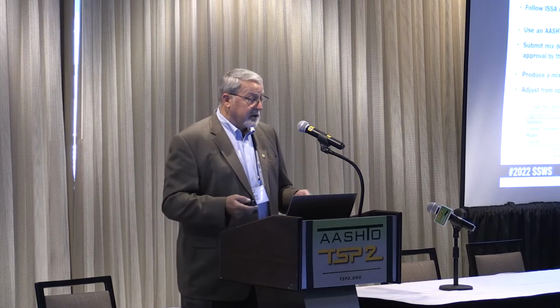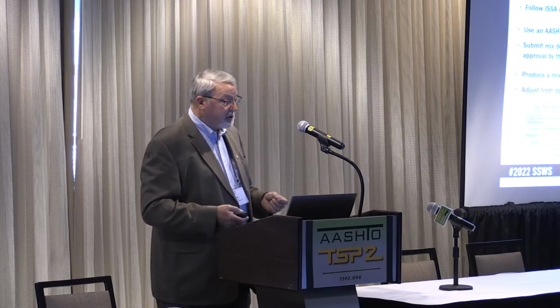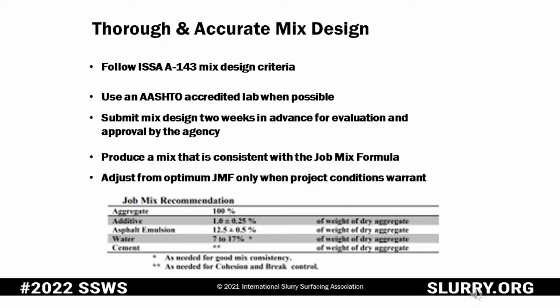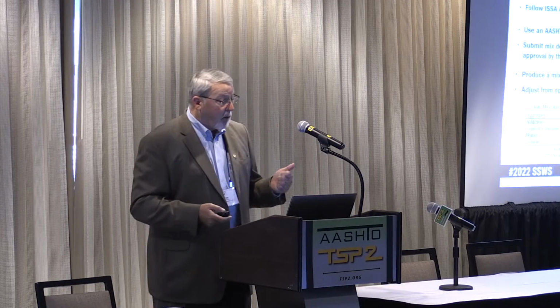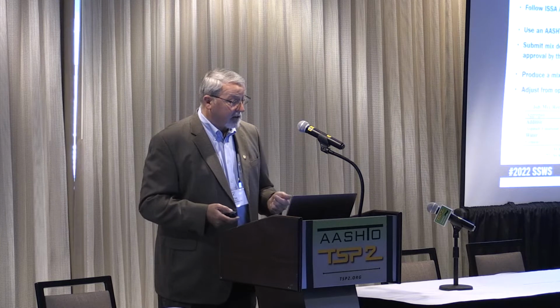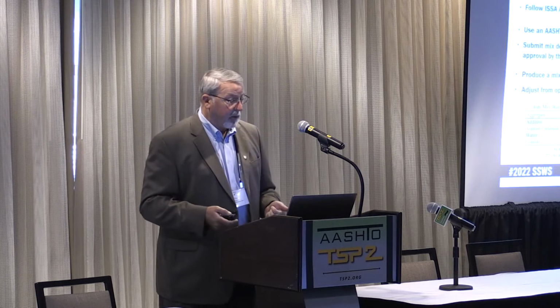You want to make sure that the contractor submits that mix design at least 2 weeks in advance for evaluation and approval by the agency that's going to be performing the oversight on the work. And you want to make sure that you produce a mix that is consistent with the job mix formula.